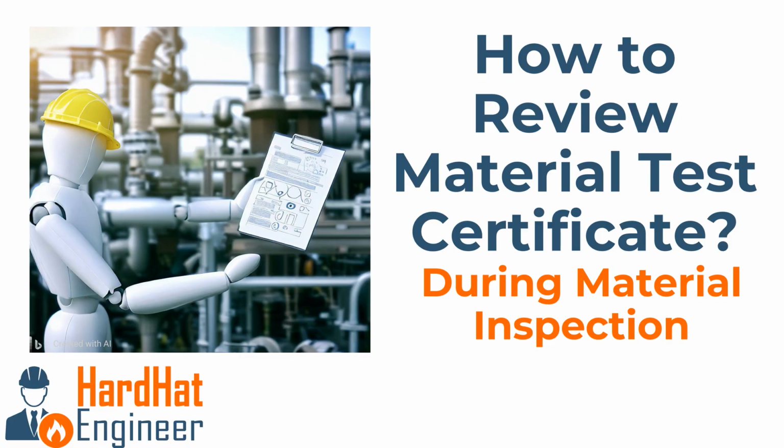All raw materials used in the oil and gas industry, such as pipes, fittings, flanges, and plates, must have a valid material test certificate provided by the manufacturer. Reviewing the MTC is a crucial step in ensuring the quality of materials used in oil and gas fabrication. The inspection engineer is responsible for confirming that the material test certificate aligns with the requirements specified in the applicable material standards, specifications, and purchase order.